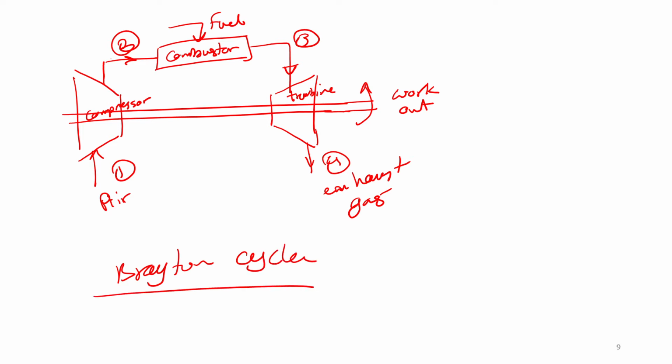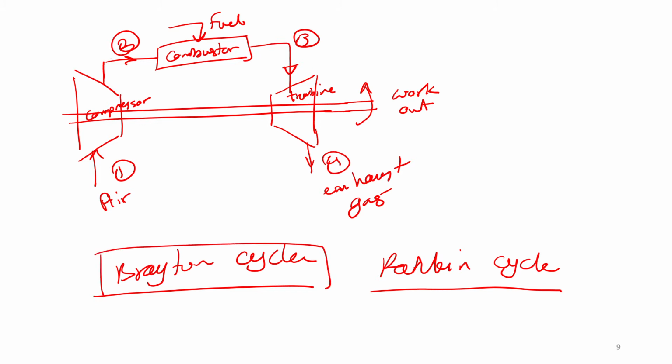Compared to a Rankine cycle, if you recall, the Rankine cycle was a closed cycle. So whatever was included in the Rankine cycle stayed there. You had a boiler and all of those things, but we don't deal with the Rankine cycle. If you ever take a power plant design course, that's all they talk about. But in a propulsion course, we are interested in gas turbines and the Brayton cycle or a modification of this specific type of cycle. So it's an open system cycle, essentially.